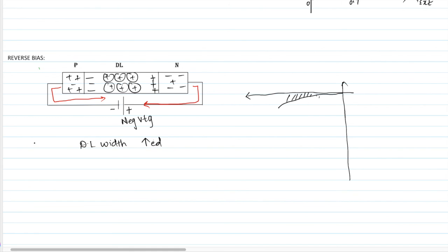And here external voltage you are increasing, so when you increase the external voltage, electrons start moving towards the battery, and hence the depletion region will start increasing, and still more increasing the external voltage, for these holes and electrons it will become very difficult to cross the depletion region because it is getting increased.